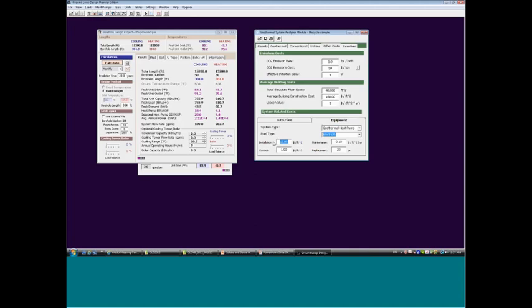What are the controls costs for this design? We're going to assume it's a relatively simple design, or somewhere in between, so it's $1 per square foot. Our maintenance costs, we have at 10 cents per square foot per year. And our replacement time, geothermal heat pumps supposedly have an average life expectancy of the low 20s. That's 20.